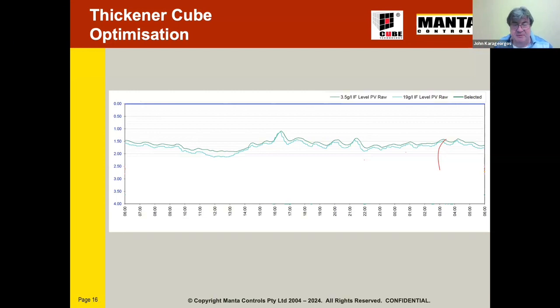So that's really important. And without that, then you're back to mass balancing your flocculant. You're going to be overdosing, which is going to cause you to have higher rake torques, which means you're going to suck the thickener out, and then you're in a mess as well.